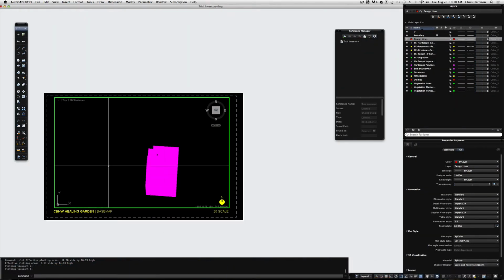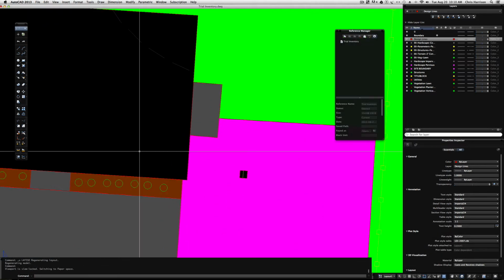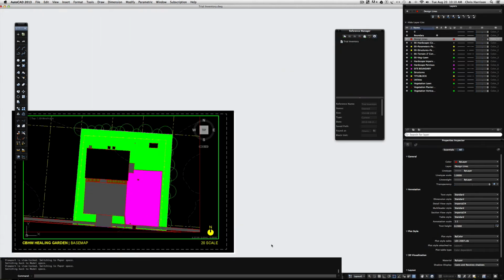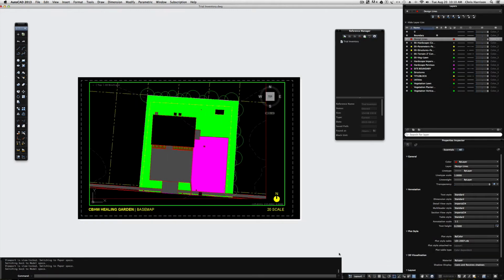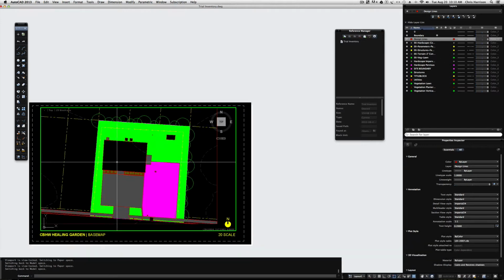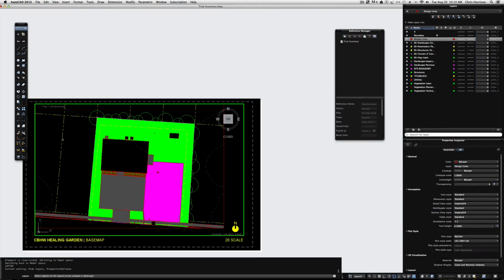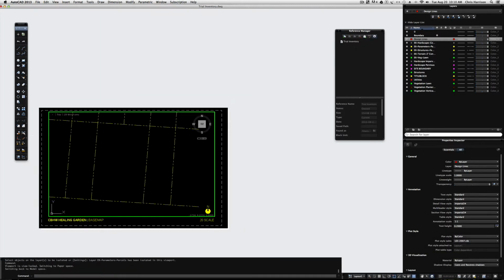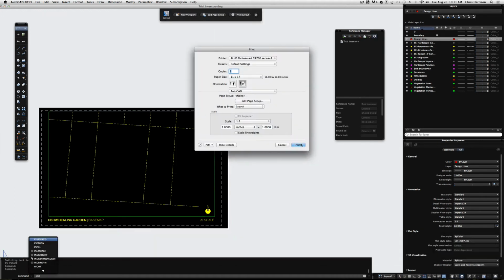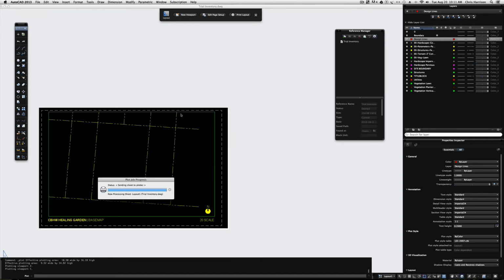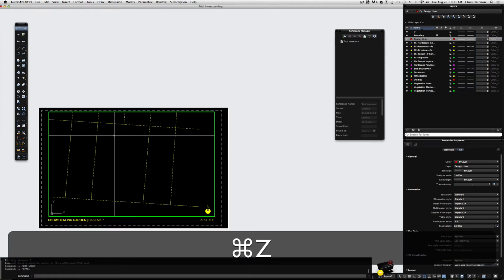So I need to get my parcels, so let me Control Z that, and I just Control Z to go back. I don't save. And those people, you can actually create different layouts and just have frozen view for LA ISO for each layout that you have for printing. But this is a small site, and I don't feel like that's necessary for this, so I'm not doing that. So I'm doing an LA ISO, and I just want to have my parcel lines there. And back to paper space, and I'm gonna go Control P, print. And also, I'm going to just Control Z that, I believe.